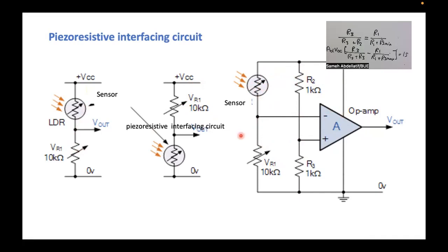You enhance the interfacing circuit quality, that's true, because you add more features, you add an operational amplifier as an active element. But on the other hand, you pay more power consumed by your interfacing circuit. And usually when we consider IoT sensors, we have to pay attention to power, because power is a very fundamental element here.